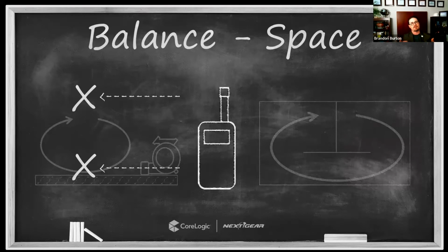Let's take a step back and understand why that's important. Again, the air that is 3 feet above or away from that floor is not the air that's drying the surface. The air that is doing the work is the air that is in direct contact with that surface. This environment, if these are drastically different, is going to dry very, very slowly. We're going to have very slow drying rates and a high likelihood of secondary damages that will occur to that surface. So it's critical we address it.